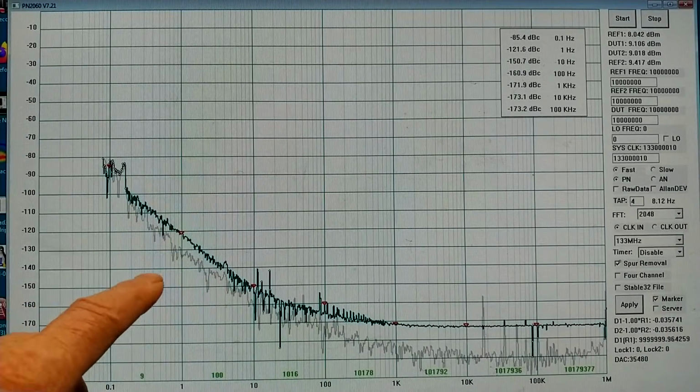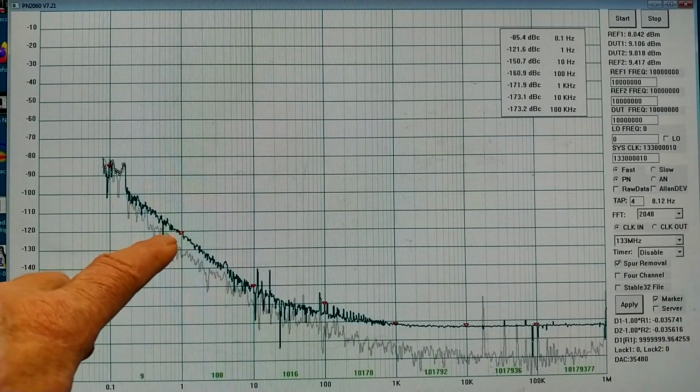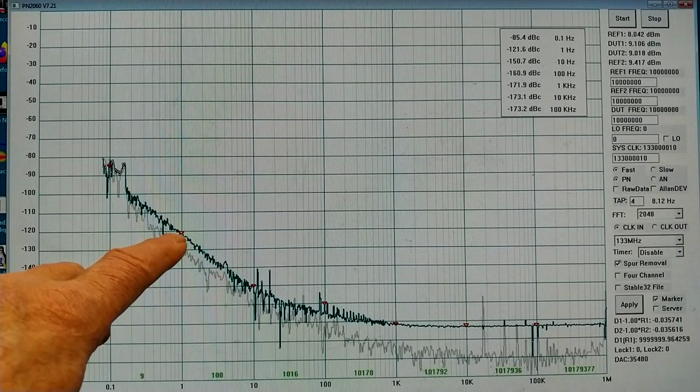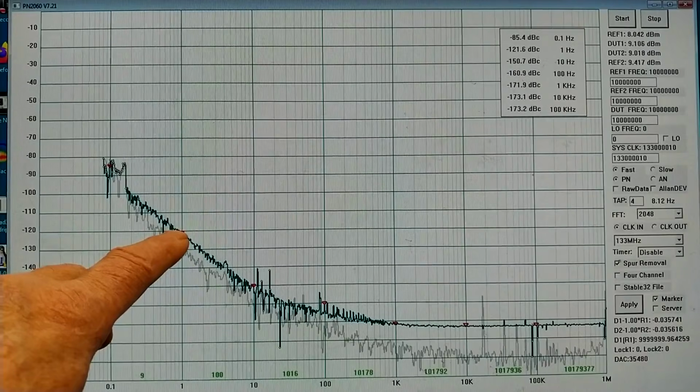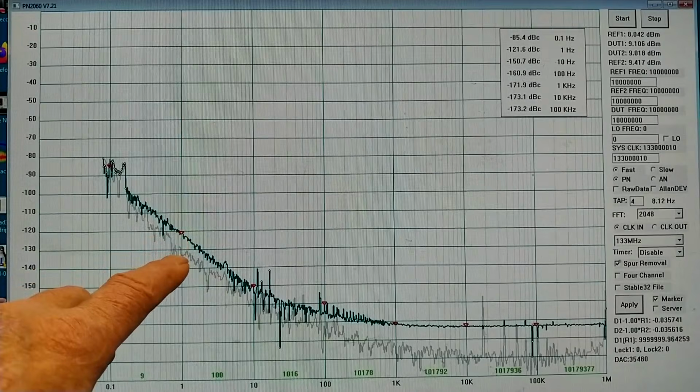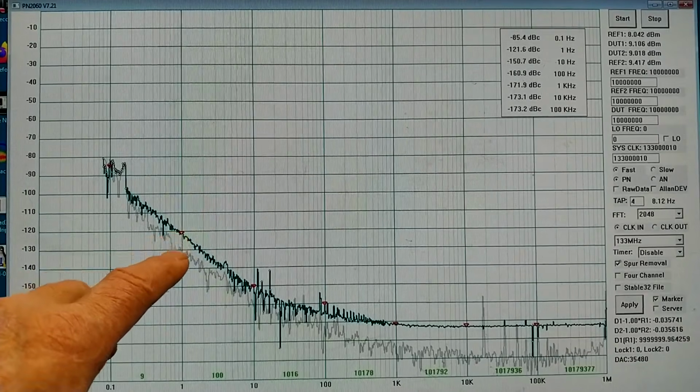This is because when it is an oscillator, there is positive feedback. At only 1 Hz offset, the gain through the amplifier is high, almost unity. On oscillation frequency it is 1.0 exactly, but 1 Hz off it is a little bit less, but still very large, and positive feedback increases gain.